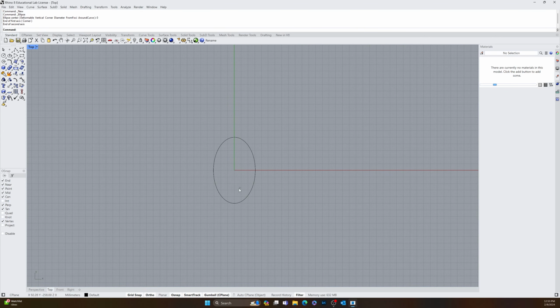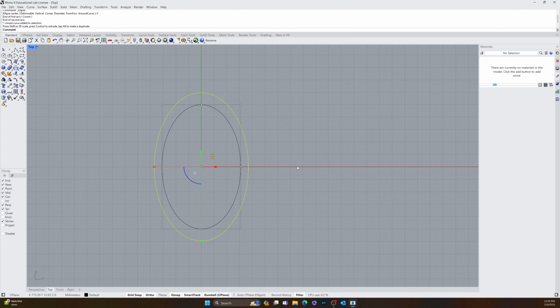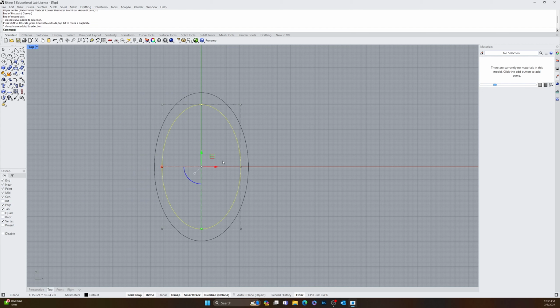And then I'm going to do another segment because it's going to have an arced out, almost spherical quality to it. So I'm going to hold down Alt and then Shift and the scale tool, and that will make a copy of that. So Alt, if you're using a PC, if you're using a Mac, I believe it's the Option button, will make a duplicate of that object. Okay, and then I'm going to make a smaller one as well. So Alt, Shift, and scale in this one here.